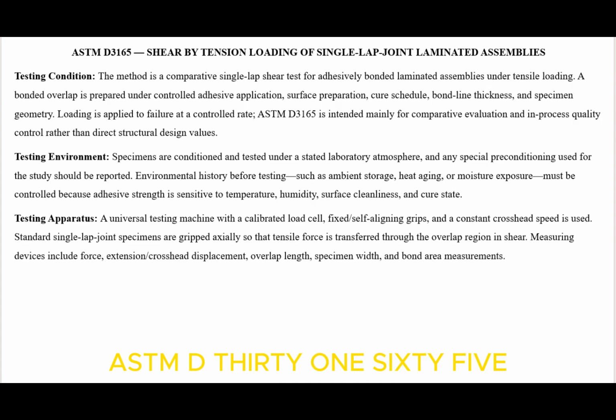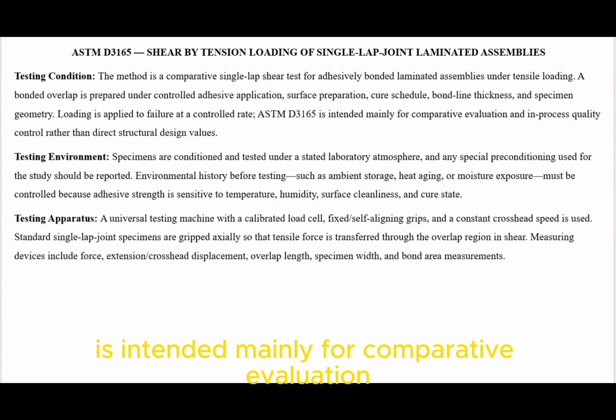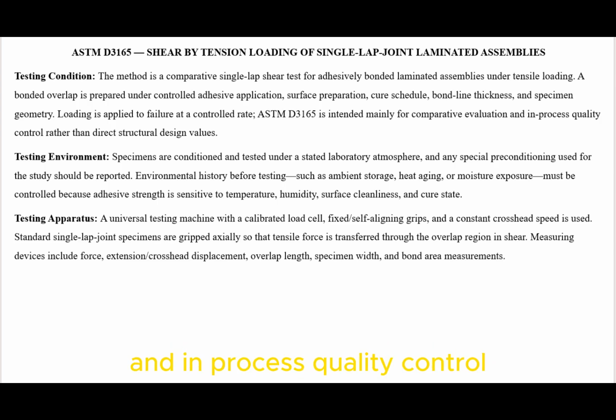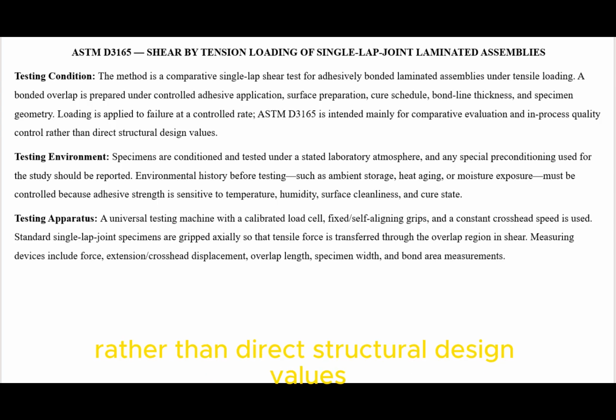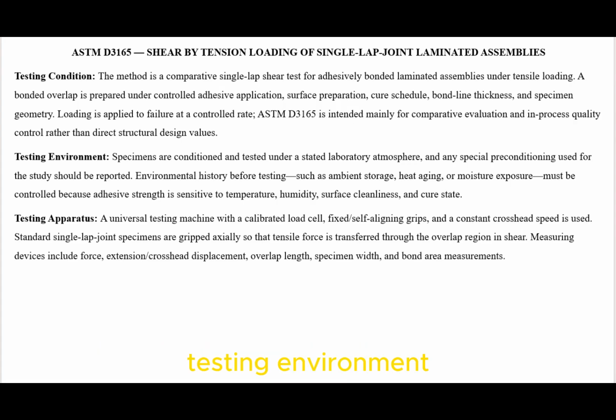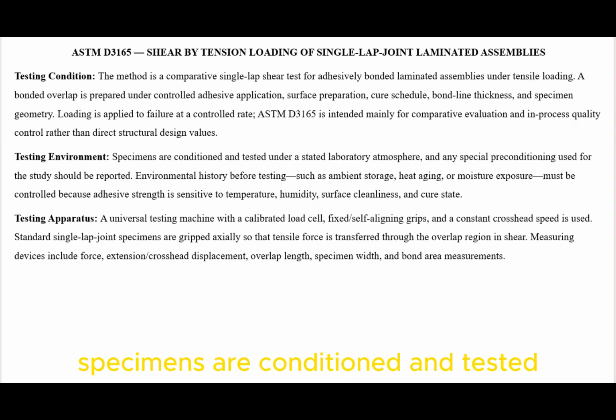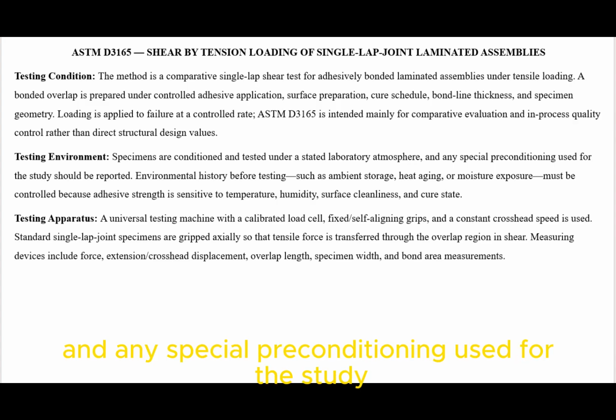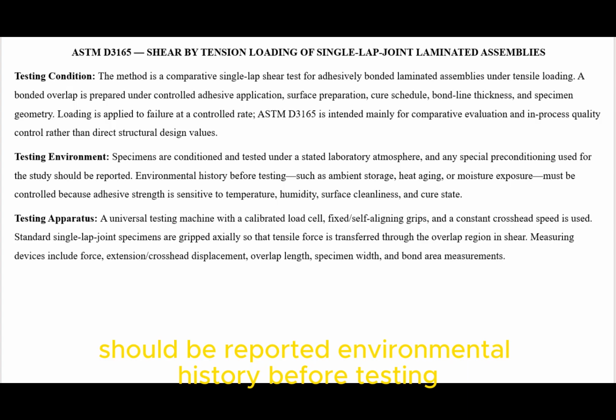ASTM D3165 is intended mainly for comparative evaluation and in-process quality control rather than direct structural design values. Testing environment: specimens are conditioned and tested under a stated laboratory atmosphere, and any special preconditioning used for the study should be reported.